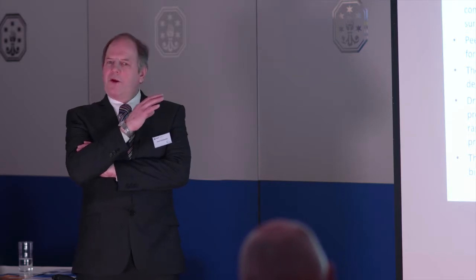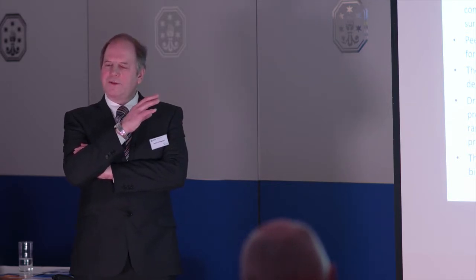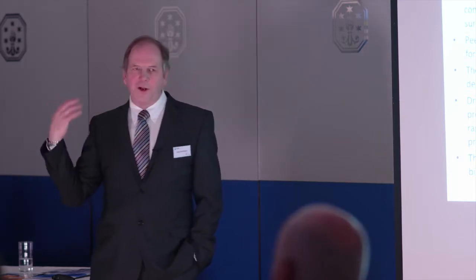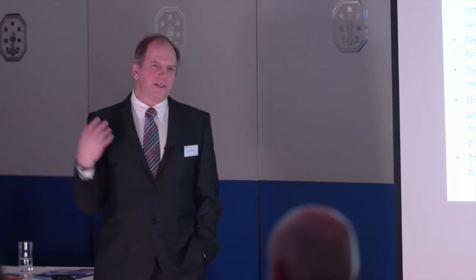Understanding where your accepted boundaries are and managing those risks, and if you limit the droplets to not being able to get through a HEPA filter, and a HEPA filter never being just the surface, are you really decontaminating that HEPA filter? Big question there. So in a fill-in line, is that really the right application? Absolutely not. In a room situation, I think it is great technology. You know, VHP is a great technology in rooms, but it's quite difficult to integrate. Dry fog, solid fog, whatever you like to call it, is fantastic in rooms.